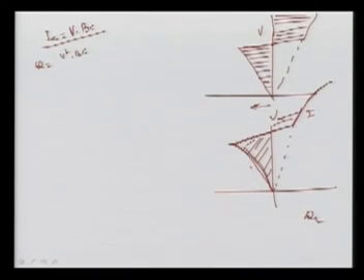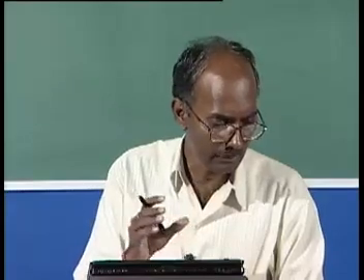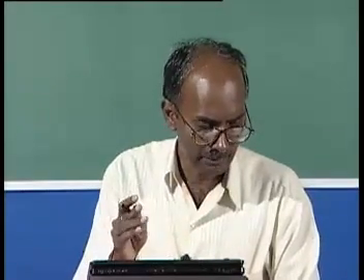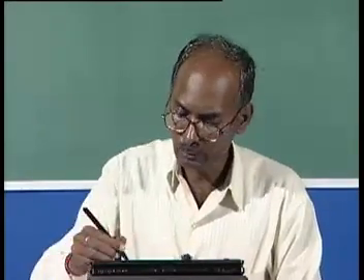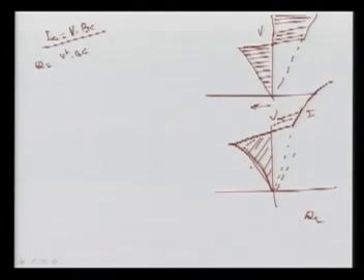Now here is another problem, the overrating, because we are having the inductor. What is the value that we can go for in the overrating? Transiently we can go into this zone as well, and we can increase. So this is the margin we can go for from there. Now let us see the STATCOM characteristic.